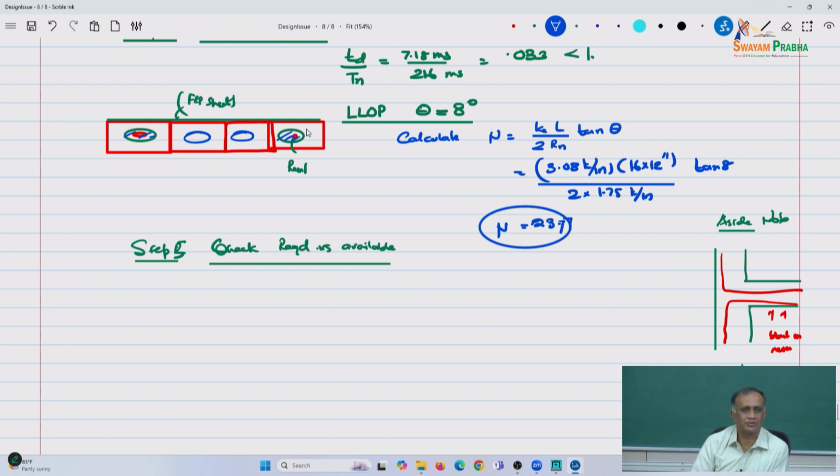Now the FRP is also going to provide you additional capacities, but not an axial capacity, so that's taken out. The stiffness it provides is very minimal. It could provide additional strength in flexure, yes, so you can get additional flexural capacity due to the FRP sheets. Yeah, I don't know of any other way to.